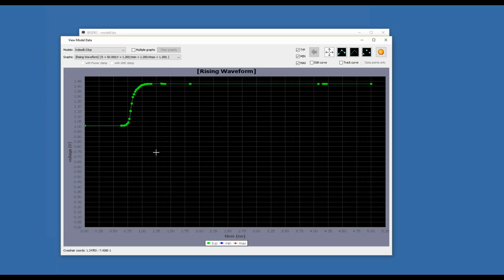So you start to see these voltage low and high DC mismatches, and that's a problem because it shrinks your noise margin. This is an LVDS signal, so the output swing should be 400 millivolts. If you start losing 10% of your voltage swing because of a model accuracy issue, that's not going to be good when you try to figure out your margins.